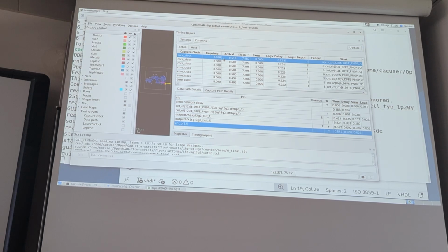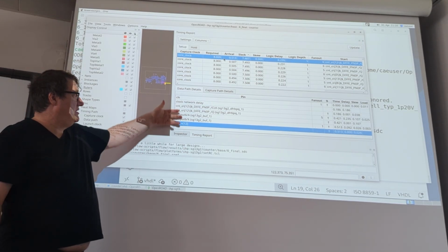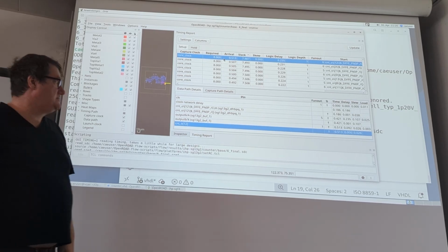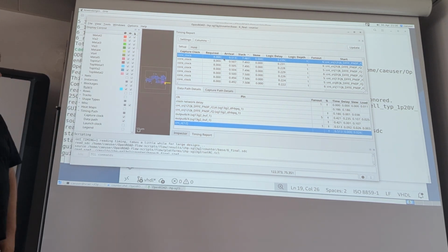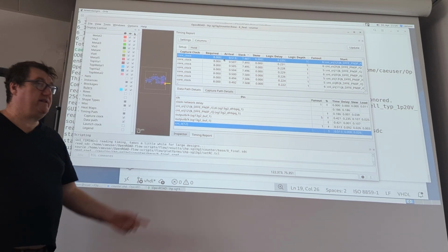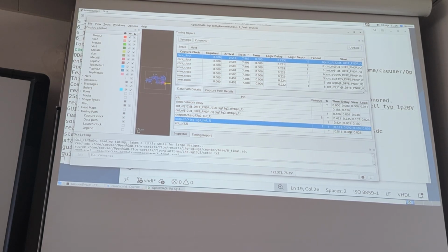And what can we do now? Because this is already a flip-flop output, there should be no logic in between here. There are only 2 buffers. Those 2 buffers, so the fan out here, introduces a 235 picoseconds delay. There is a fan out of 5, so some flip-flops attached to it, but there is a buffer introduced, which adds a small portion, but this is really not a lot yet.